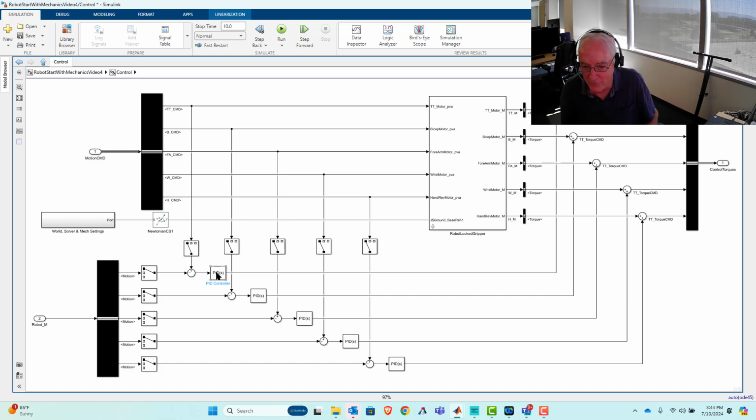Perhaps we'll have deeper conversations on this idea of what feedforward is really doing. But I'd say that if my feedforward controller is predicting useful torques, that is only going to be true if the state of this system, meaning the position and velocity of every one of those axes, is going to be identical to the plant.